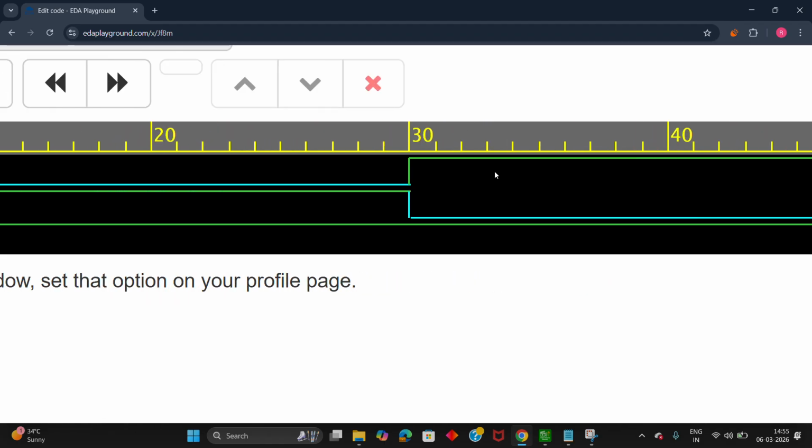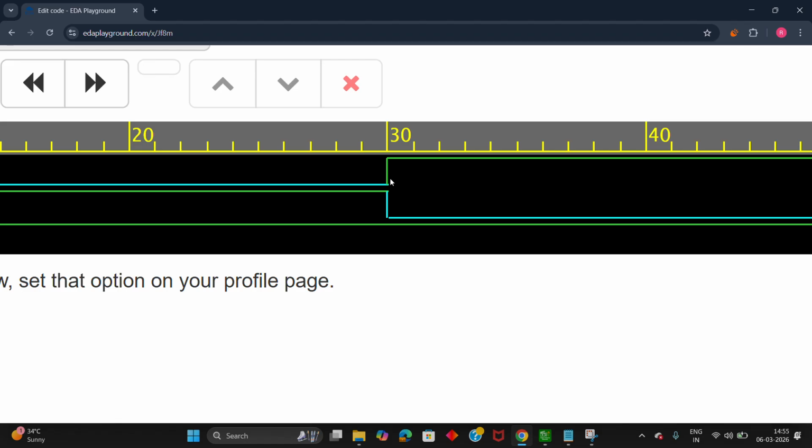At 30 nanoseconds point of time we are going to make our input test case a is equal to 1 and b is equal to 0. Sorry, input test case b is equal to 0 and input test case a is equal to 1. For those corresponding inputs we are going to observe the output as 1. There is no change in the output till now, for all the three test cases: 0 0, 0 1, 1 0.